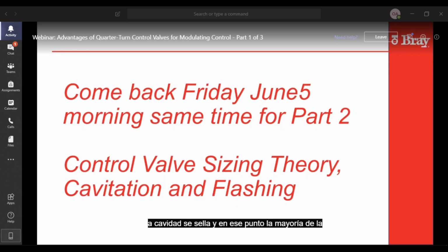And at that point, most manufacturers have a drilled ball. So there's a little hole right where the stem goes through, and that little hole takes that pressure and brings it inside the body of the ball as well. So it becomes a bigger cavity. And also the seats are normally made to burp downstream or upstream, depending on the valve style. So normally there should not be overpressure in that cavity area, but the process will be there no matter what.